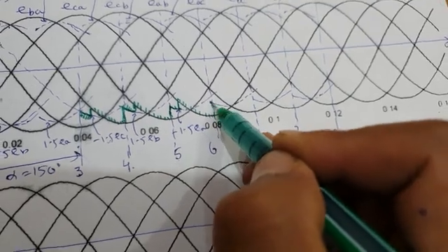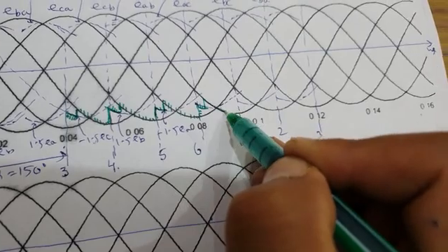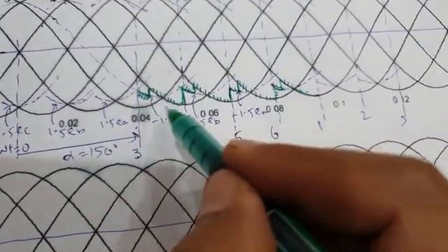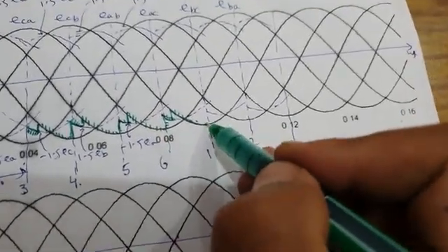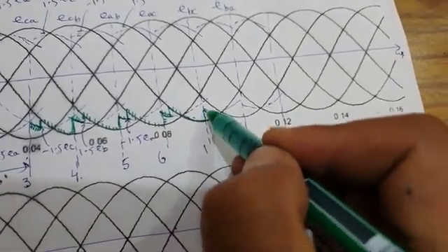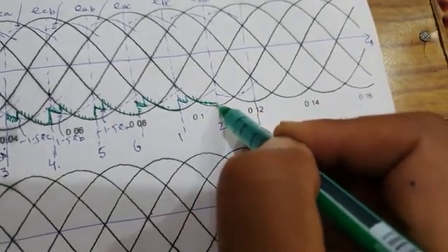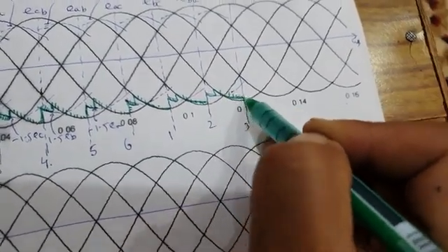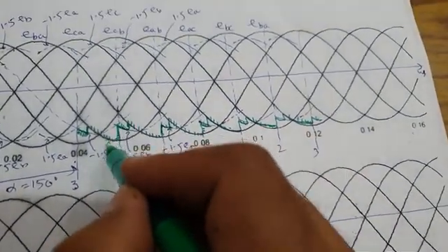So continue like this blindly. You don't need to see the table. You only need to know the first instant, the first 2 segments. The remaining segments just follow the same pattern. That's it. We got it. So this completes our load voltage waveform VD.